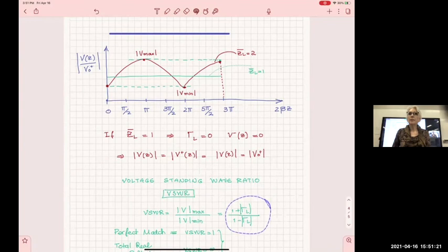Yes. So in this example, we used a voltage source that was ideal and didn't have internal impedance. How would that affect the V over V? It will not change this pattern at all. All right, it will change only V naught plus. It affects only how much of the total power that the source can generate eventually goes into the input port.